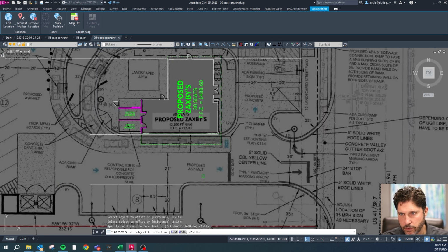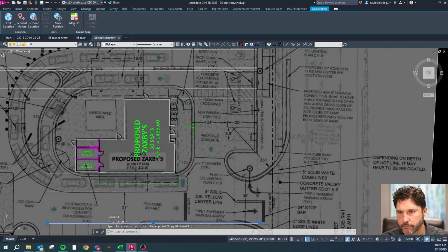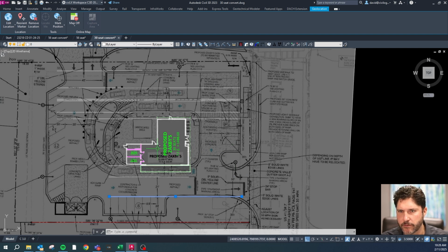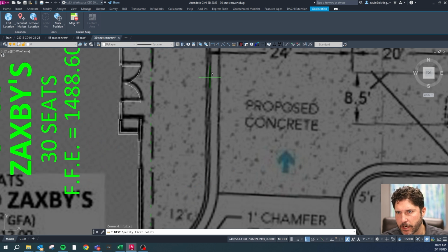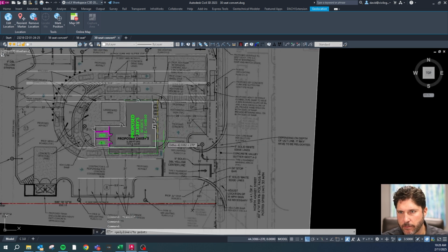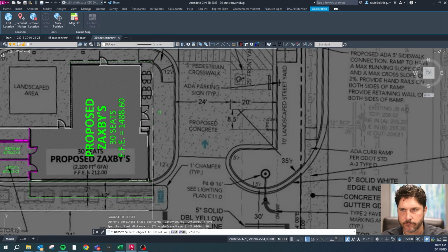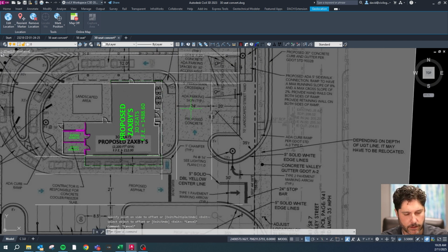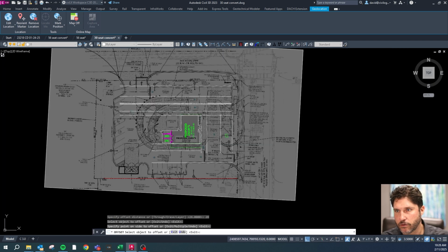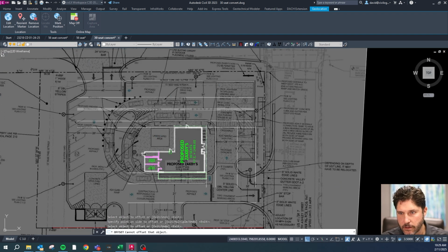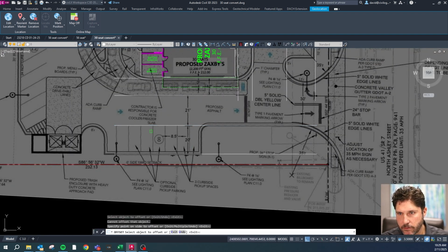So you can see we're just doing a wireframe. Same thing that we do on a lot of other deals. Now it looks like this road is a little bit crooked, maybe just because of the orientation of this site. Well, if we're doing a template, we don't want it to be crooked for all sites, so I'm going to pick a number in the middle here and make it orthogonal. It's about 10, so I'm just going to make that 10. 10 feet, 24 feet, 20 feet. These should be 20 also. Those are 20.